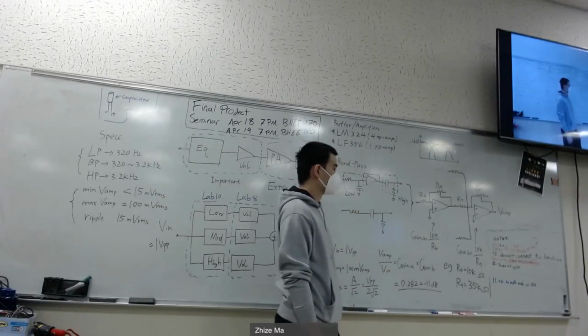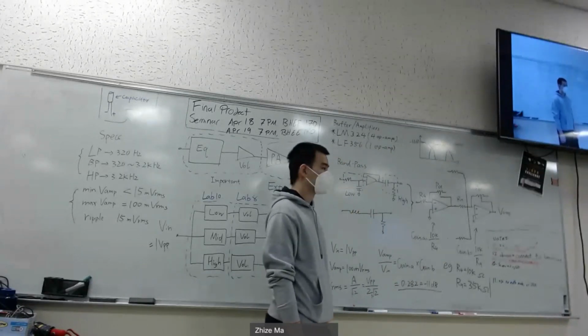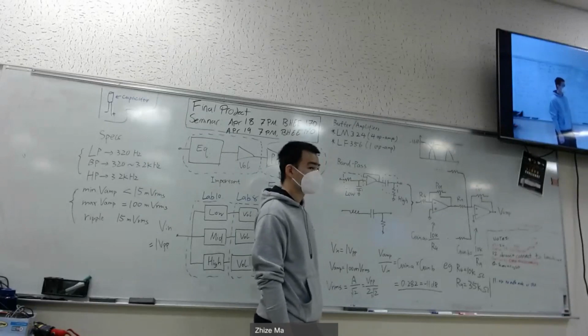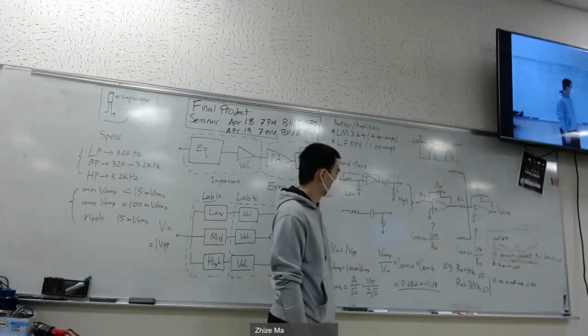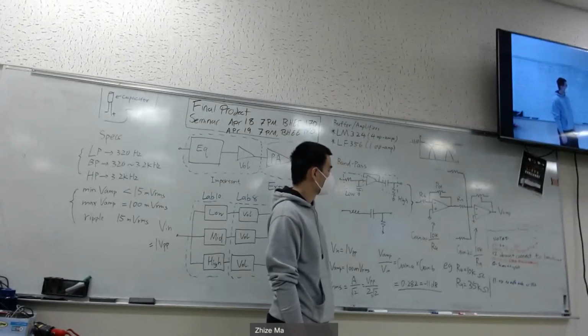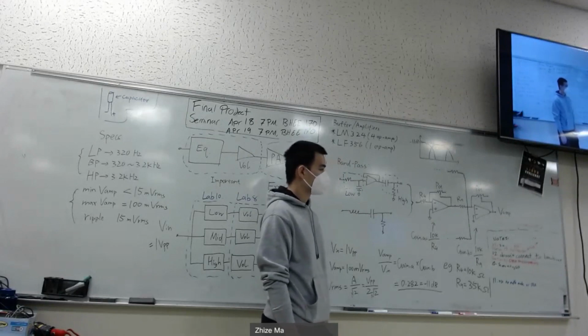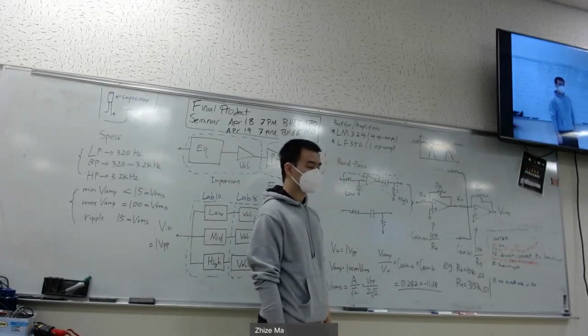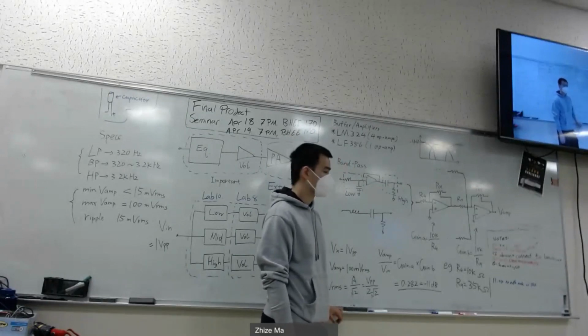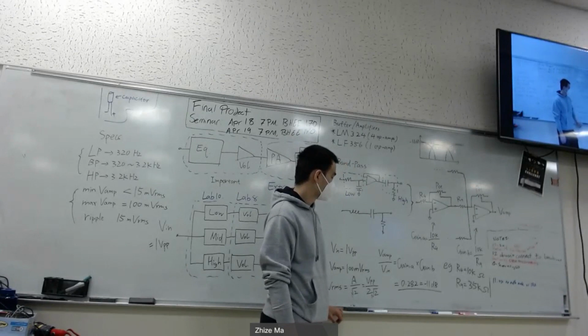So all that stuff's at really low power. So even though you're able to filter it out, you're able to make that band, you're at a really small gain at that. And that's if you just do a standard inverter like is on the board right now, you're not adding gain to that. You're just putting out whatever you're putting in. So if you bump up the gain on that, usually a gain of 2 or 3 will work just fine if they really want to. I've seen one person last semester do a gain of 10. It was able to get out, and it was really loud. It was just terrible quality.